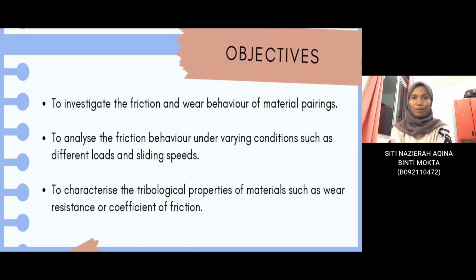I will present about the objective of this lab, pin on disk. First is to investigate the friction and wear behavior of material bearings. Second is to analyze the friction behavior under varying conditions such as different loads and sliding speeds. And the last one is to characterize the tribological properties of materials such as wear resistance or coefficient of friction.